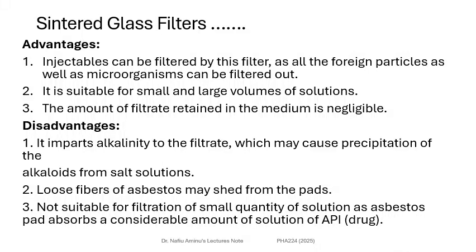When we say parenterals, we are referring to those solutions that are meant to be injected, directly into the body system. So in addition to the requirement for absence of microorganisms, there's also a requirement of absence of any foreign particles. So these sintered glass filters are a good choice in trying to achieve that goal. So it's one of their advantages.